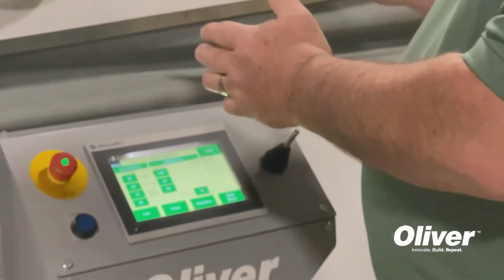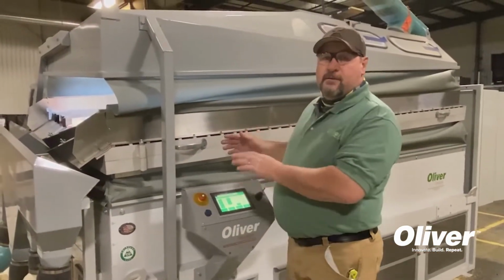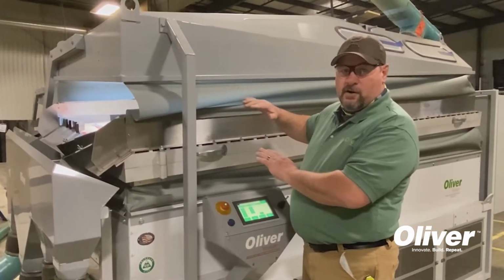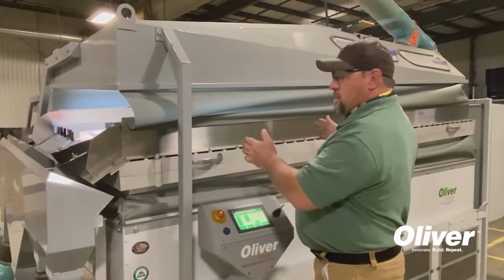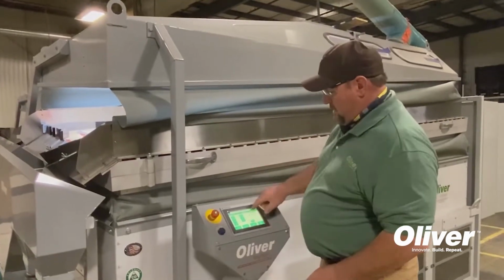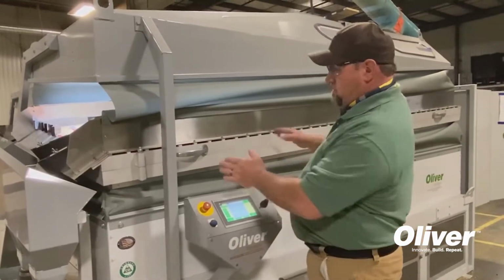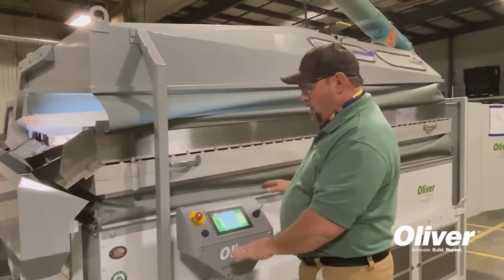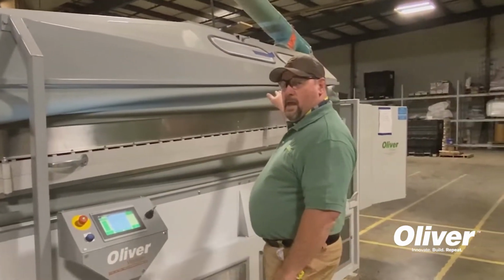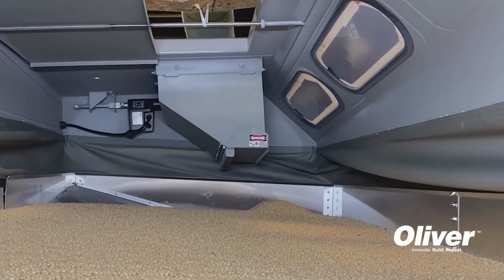We first start off here with our side tilt. Our side tilt is the pitch of our table. This is the incline or the resistance we give seed on our table. That is set by a feedback sensor on our hydraulics that allows us to easily set any number we want for percentage, and we can adjust our side tilt accordingly. Our end raise is done the same by adjusting the end of our table and giving us more or less dwell time. Our next key adjustment is our feed rate.